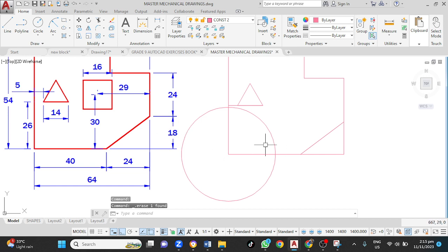So I could use line from here. I could go draw a line on this existing line up 30, then out. Or I could track that point. So let me go line, left click here, then track that up, type 30, 30, enter, then draw this out, 29, 29, enter, enter.